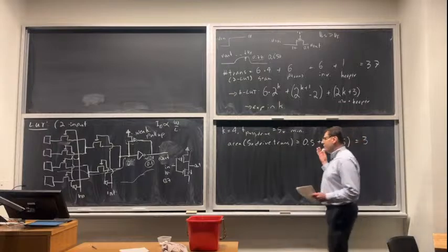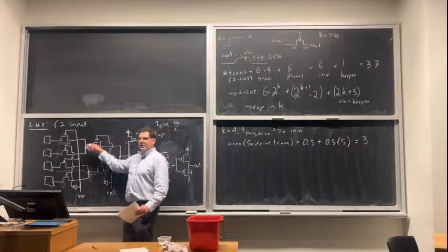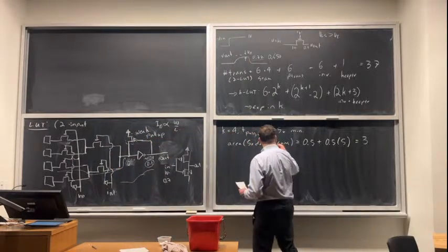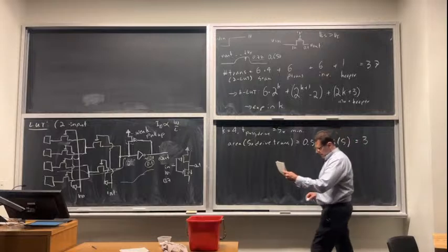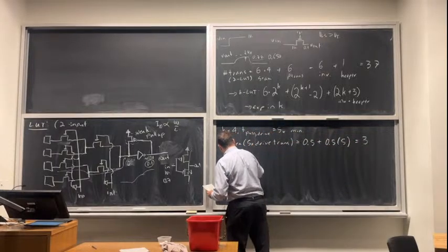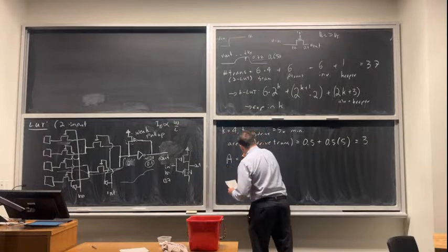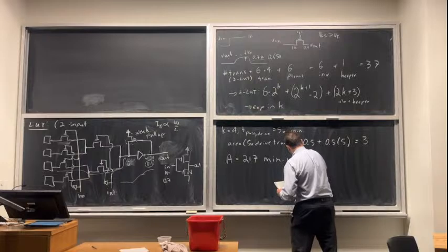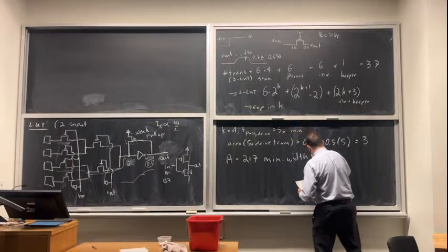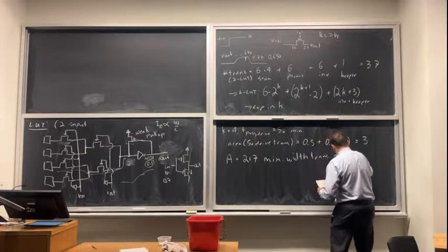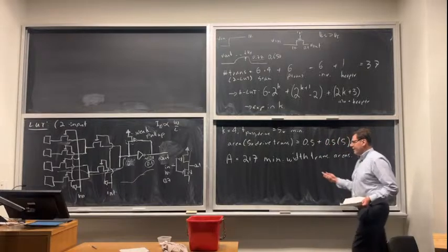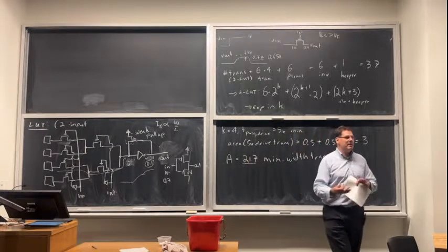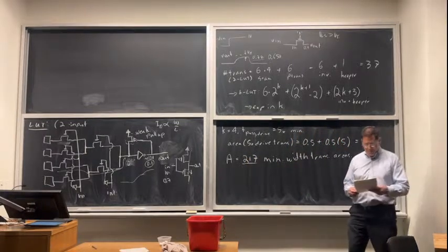So it's 5 times the drive strength, but the actual area I need, including the spacing to the next transistor and everything, is only like 3 times bigger. If I plug all of that back in there, I would get the area is equal to 217 min width transistor areas. Okay, so this is like a process technology kind of independent number. It's like I need like 217 of the smallest transistor areas I could make that are kind of useful.